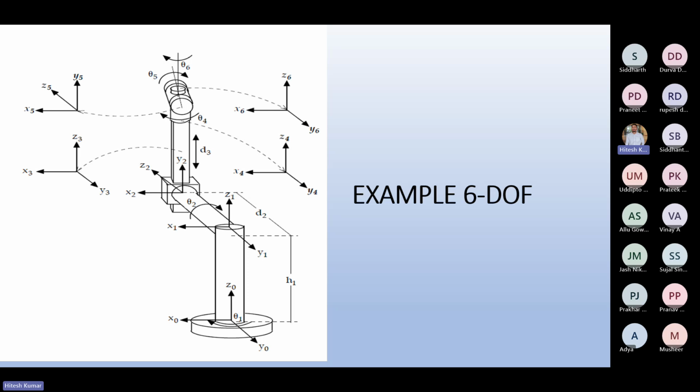So from the transformation matrix we will get the orientation, the directions, in short the direction cosines, which tell us in which direction the x axis, y axis, z axis are transformed with respect to the base axis. Orientation will give us the direction cosines, and position will give us the coordinates. Understanding position and orientation, mainly it is a combination of both. And the last row 0 0 0 1 will be common for all, to make it easy to multiply the matrix.